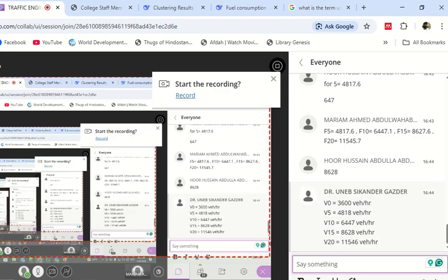Okay, you can go back and do the level of service analysis in the same way we did in the previous question using these values. Free flow speed is given, so you will start from the step after that. We have done level of service analysis using the V values earlier, so instead of doing it one time, you will do it with each V value. This is one way of doing it.